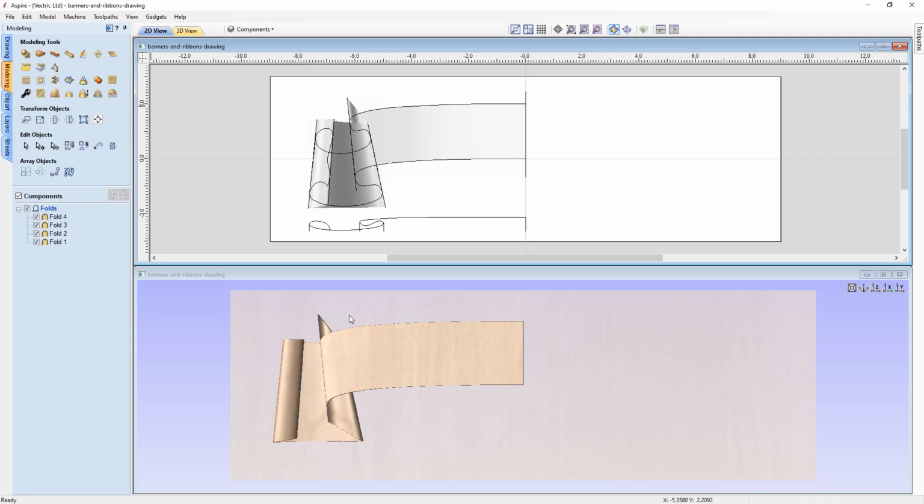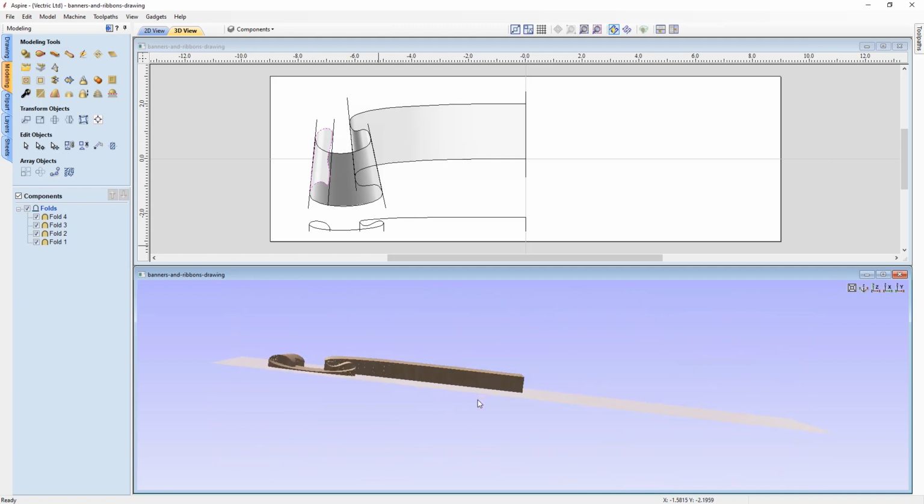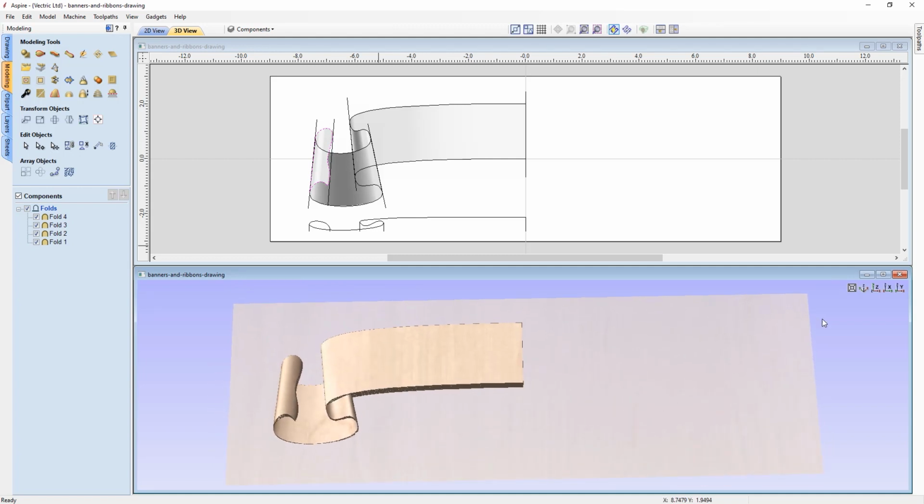Now let's go ahead and crop these components down to the shape that we need. So let's choose this vector, holding down my shift key. This component will clear outside that vector, and we'll do the same for all of the rest of these folds. And now you can see in our 3D view what we were trying to achieve using all of these drive rails, closed vectors, and cross sections. If we take a look at that, that looks pretty neat. And I'm really quite happy with that.